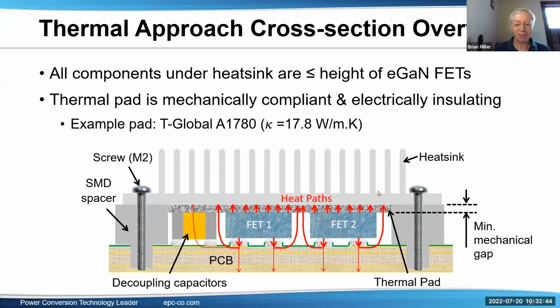It's a cross section. You'll see the heat lines in dark red are the more primary path of the heat. You'll see smaller ones, smaller conduction paths. You see a capacitor in here. That's not bad because the capacitor can act like a bridge to take some heat from the board into the heatsink, which is good. So that's not a problem to keep this all clear. Other parts to fill up the gap is actually good.